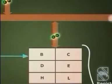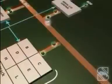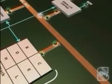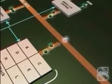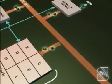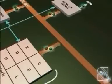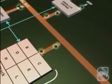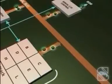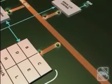General purpose registers. In Intel 8085 microprocessor, there are 6 8-bit general purpose registers. They are B, C, D, E, H and L. They may be used individually or combined as register pairs to perform some 16-bit operations. The permitted combinations of register pairs are BC, DE and HL. The HL register pair is normally used to form a 16-bit memory pointer.